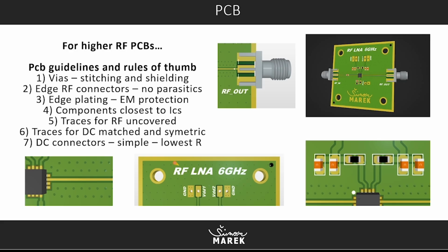But also through-hole technology has a negative influence through parasitics and unwanted behavior for RF and very high frequency microwave design.